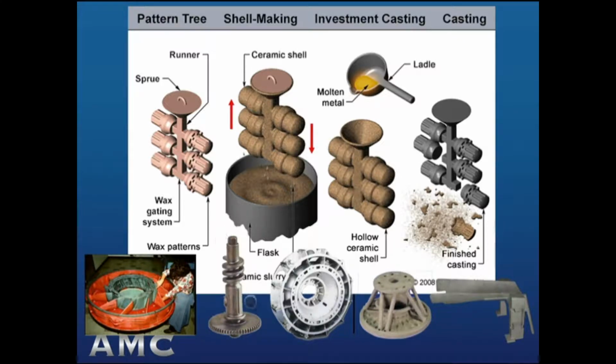Some more complicated castings, as an example there in the center and center right, but then a casting that I made with the Army, which was kind of a breakthrough casting, an example of why the hot mold can be really important. This is a 17-4 PH high alloy steel with a 2 millimeter wall thickness on that curved plate section over about a 500 millimeter length.